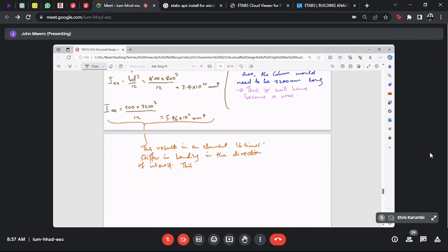This is the basic concept of the retaining wall. No, not retaining wall, but of the shear wall. That we can actually just rearrange whatever column we have and convert it into a wall, and for the same amount of material achieve a lot more stiffness in a particular direction and therefore stiffen the building significantly in that direction.